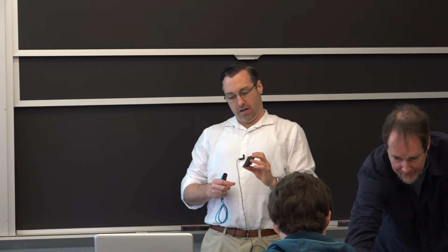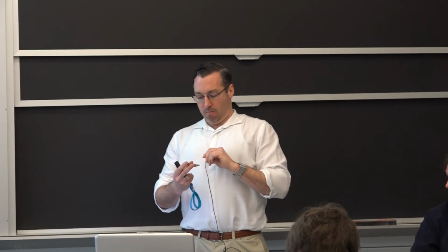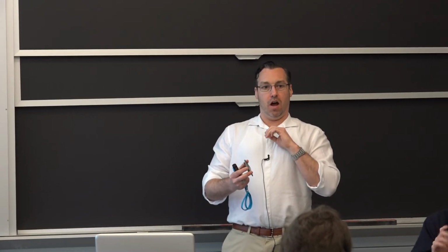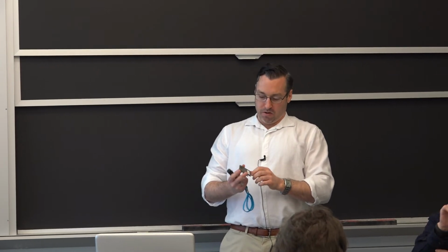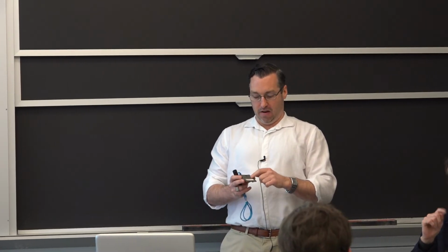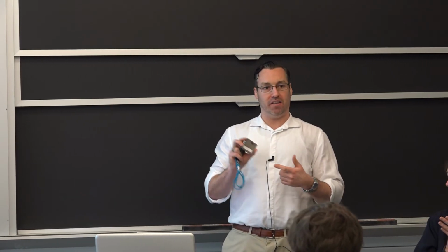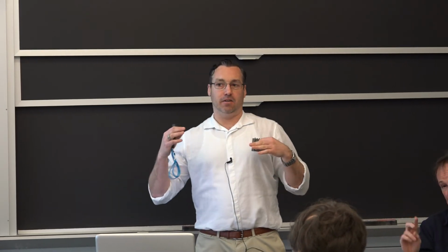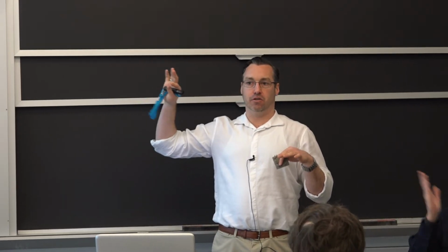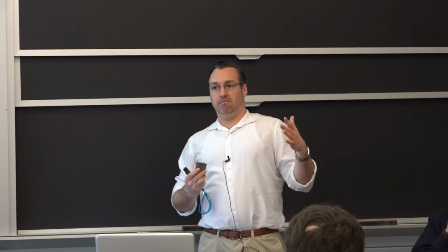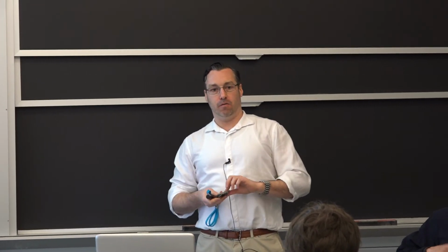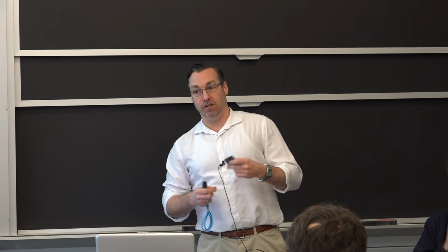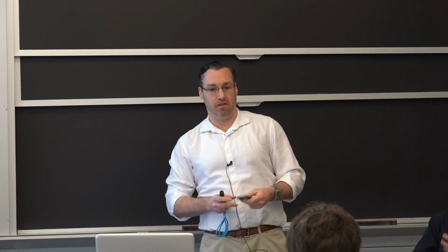The other thing on here, this is a duct segment. What you'll see is when they do non-destructive testing on it, for this, they'll do eddy current tests. But what you'll see is this part got rejected for a crack above 20 thousandths. So we're not talking about really large cracks like you'd see on structures, whether it be a bridge or something else, where you actually can tolerate larger cracks. For airplane engine sections, these parts will get rejected if the cracks are thousandths of an inch.